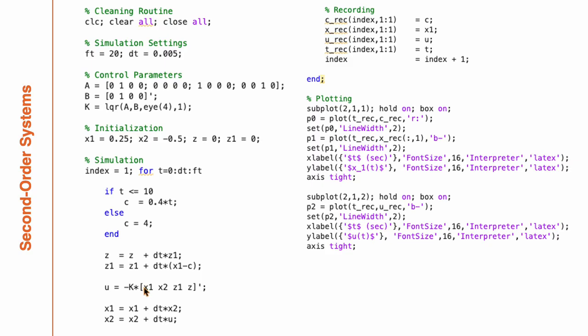My expanded state space will have 4 variables. This is my initialization, my integral initialization, almost always 0. And this is our A and B that we established from the expanded pair. I am just using first the most basic identity for Q and 1 for R. And the rest is recording and plotting.